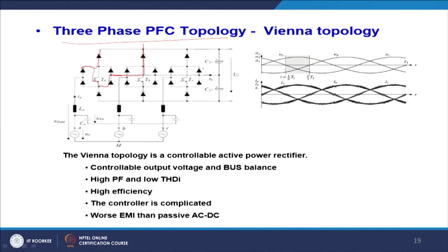So, you get 3 volt, and there will be a switch that also gives you around 2 volt; sometimes if it is a high rating IGBT, then a 5 volt drop will be there, and if it is carrying 100 ampere of current, each of the sets will give you 500 watt of losses. So, it is equivalent to running a 500 watt motor. Since you are not using it as a room heater, there is no purpose in having this kind of configuration,